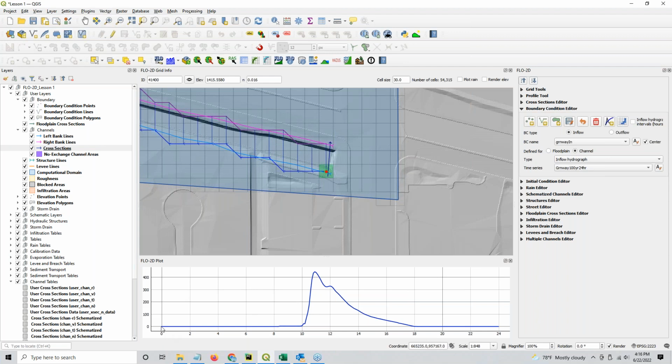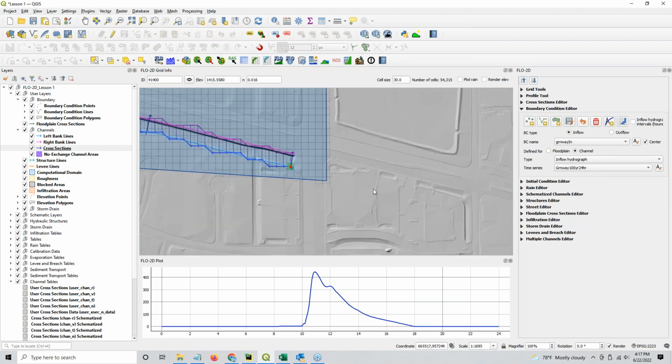Well, if you bounce that up too high too quickly, it's going to cause instabilities. So just ramp it up over like the course of an hour instead of over the course of, you know, 1/10 of an hour or 0 to the next time step if you're using like 6-minute intervals or whatever.